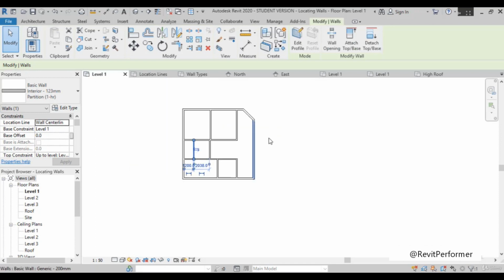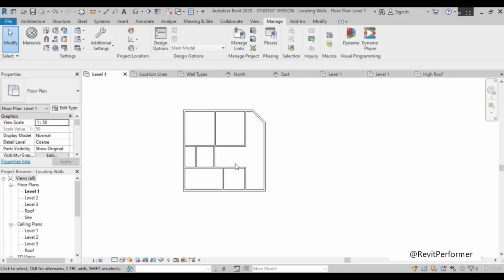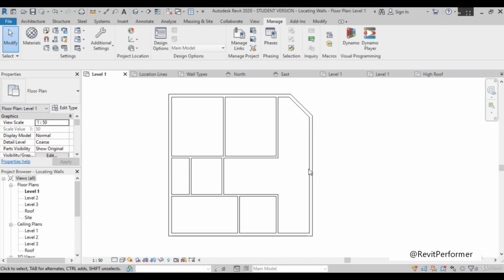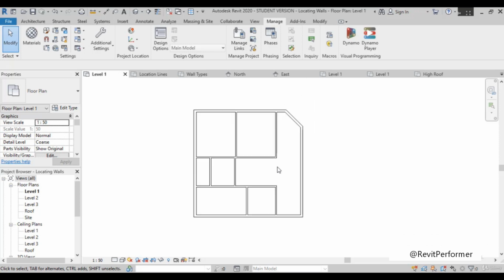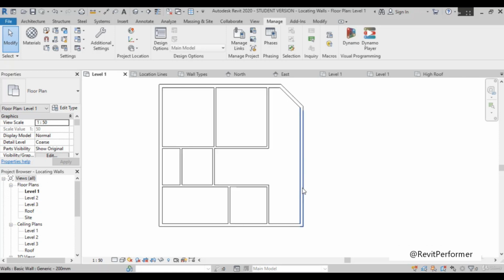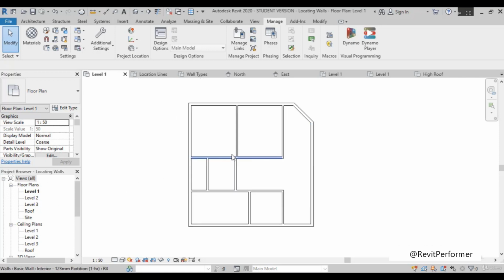But you can see, first you will sketch the whole plan that you have. Okay. And then you can manage it by using the dimensions. Okay, so this is really important, and one thing that is very important right now. Whenever you do, just be careful of the levels that are used. That is, if you use level 1, it will show in floor level 1, and if you use floor level 2, so in this project browser, that is very important.